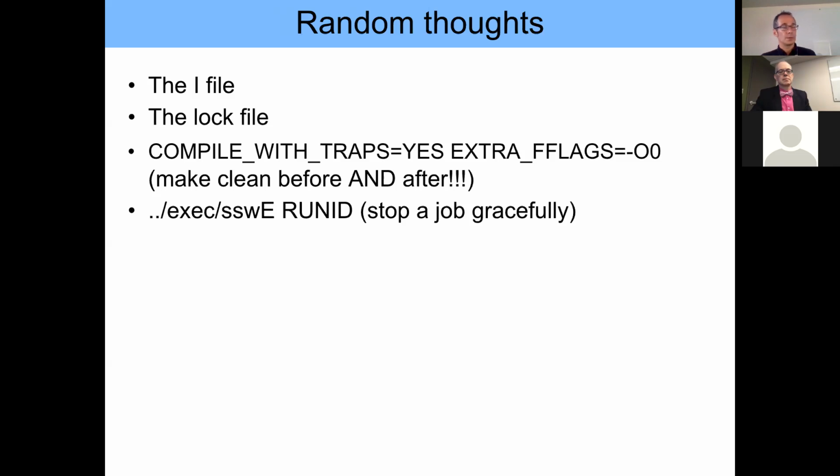Again, for safety, probably, or maybe because the model literally crashed and there was no time to do any cleanup. So when you fix what happened and you want to continue the run, so maybe you change something in the input file, it's very frequent that this is one of the scenarios, then you have to manually delete this log file, which says essentially to the model, okay, I know I am going to rerun something in that pre-existing directory.